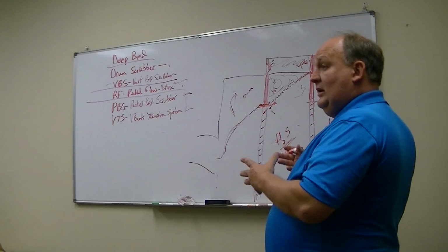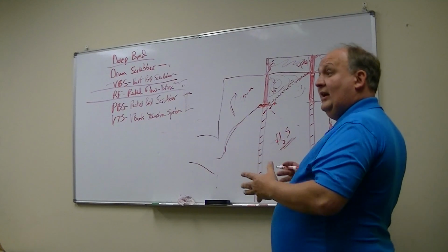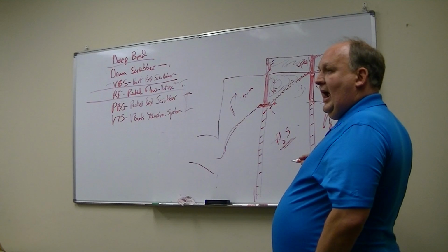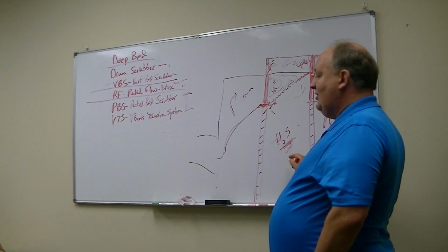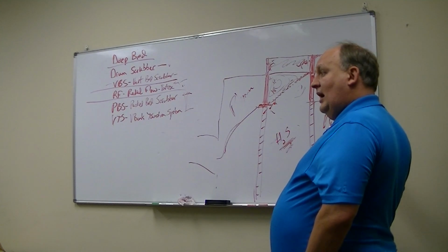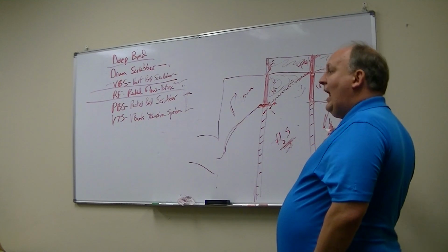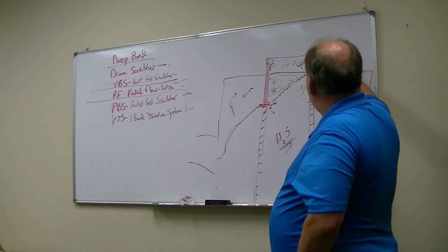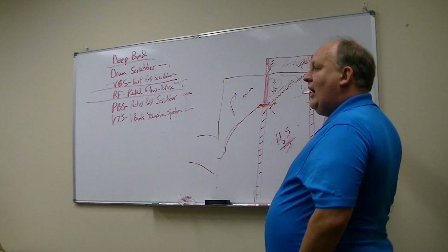They tried our media in a test rig, and it worked really, really well. Then they put it in this system, and the system kept taking out the hydrogen sulfide, but it kept letting some dimethyl disulfide get out. Not a lot, but enough that they were unhappy with it. And they blamed it on the absorbent media, when clearly it's a design issue, it's an airflow issue.